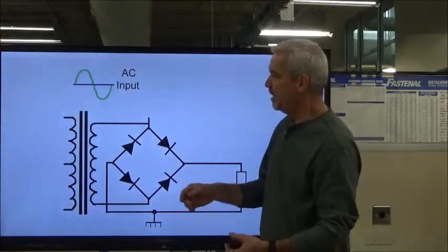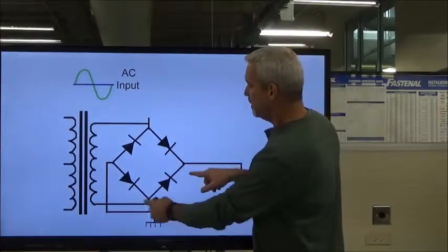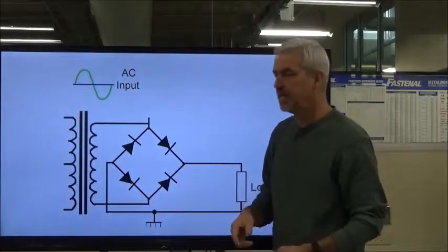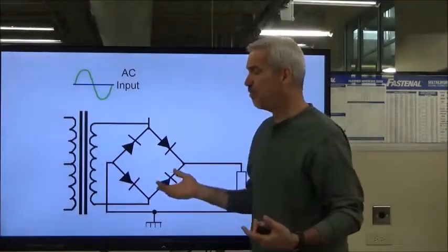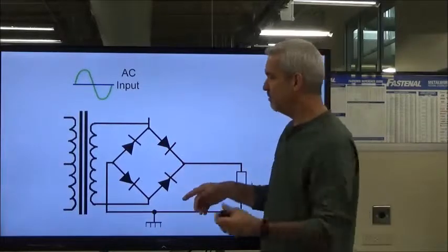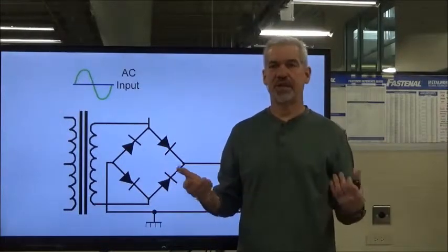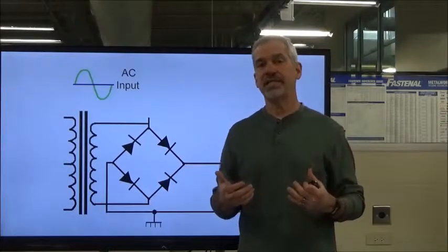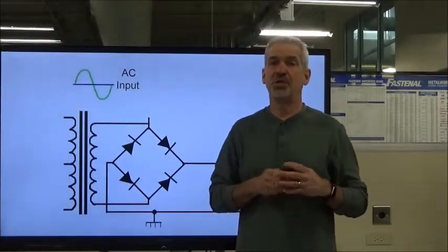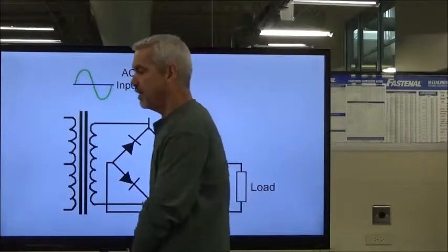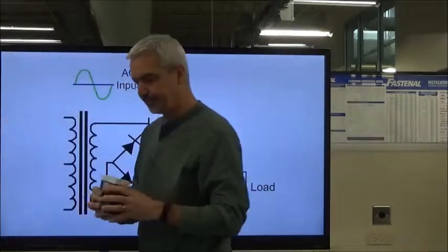All right, and then check to see if you've got DC voltage. Switch your meter over to DC, whatever it's supposed to be. If it's supposed to be 24 volts, put it on something higher than 24 volts, obviously, and measure to see that you're getting DC voltage out. That in a nutshell is the easiest, and probably about as deep as you'll go when it comes to a power supply. I'm going to use this as an example again.